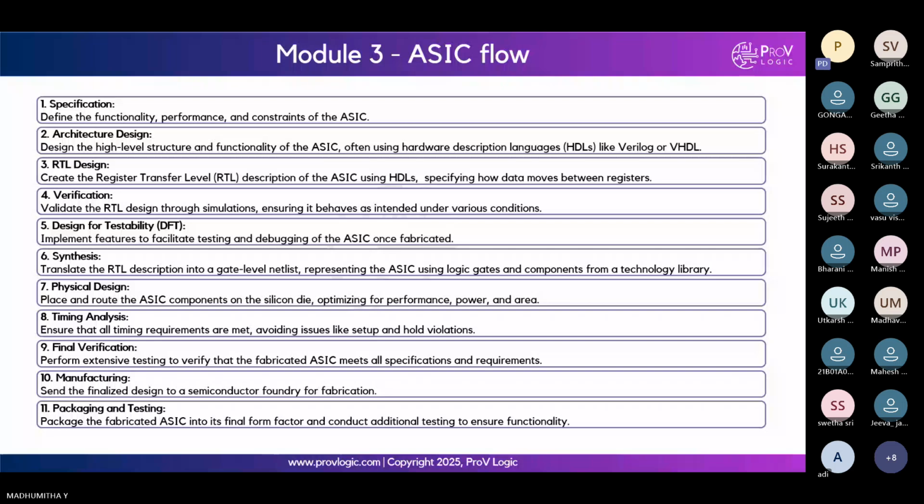How is the PD engineer going to fix the area in PPA? For this, we have many optimization techniques. We have cells with multiple areas, so we can change the cells to ones with a lesser area and we can follow some optimization engines by the tool. This part I will explain later.